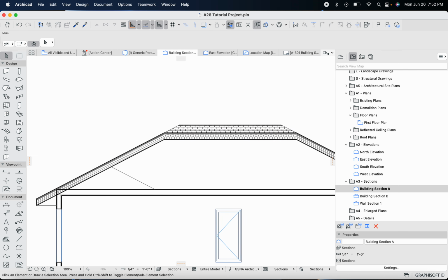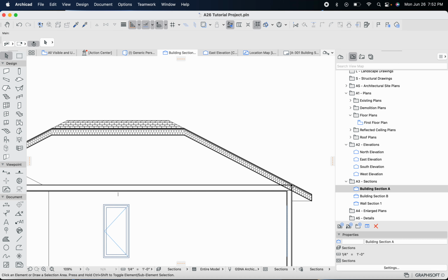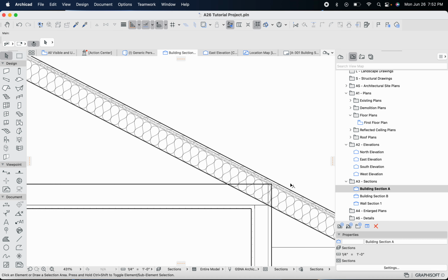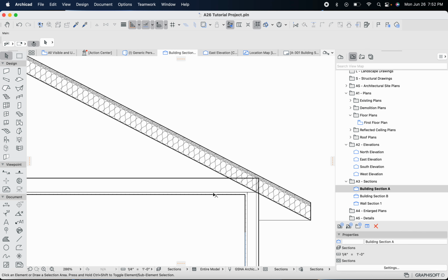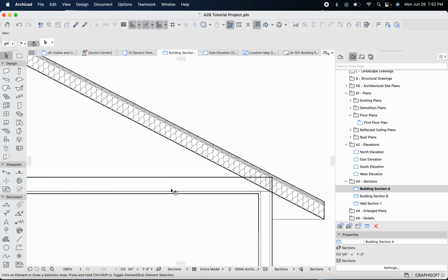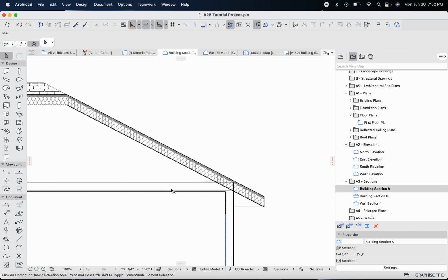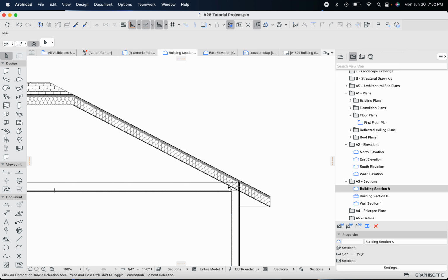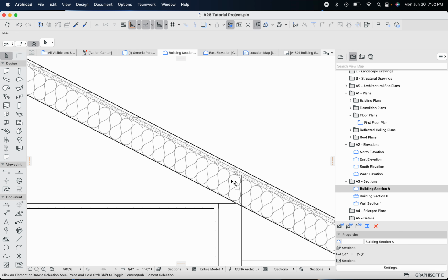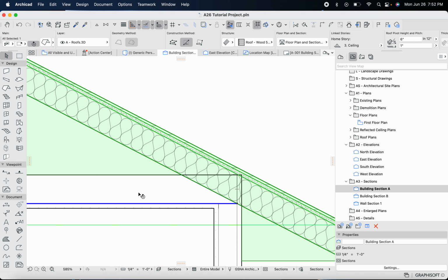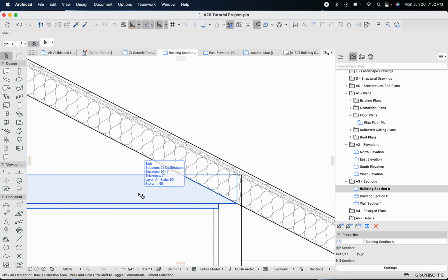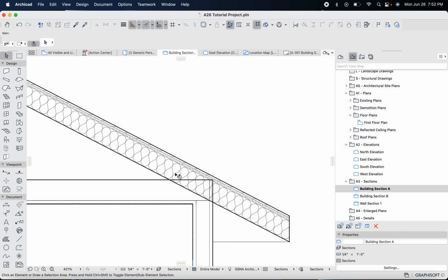Okay, so that's that. Now the cool thing about doing the 3D modeling is, depending on how you're setting your roof structure, if you're trying to use the ceiling joists as rafter ties, you want to make sure that your rafters are actually bigger, or at least the same size as your ceiling joists, and that doesn't always happen.